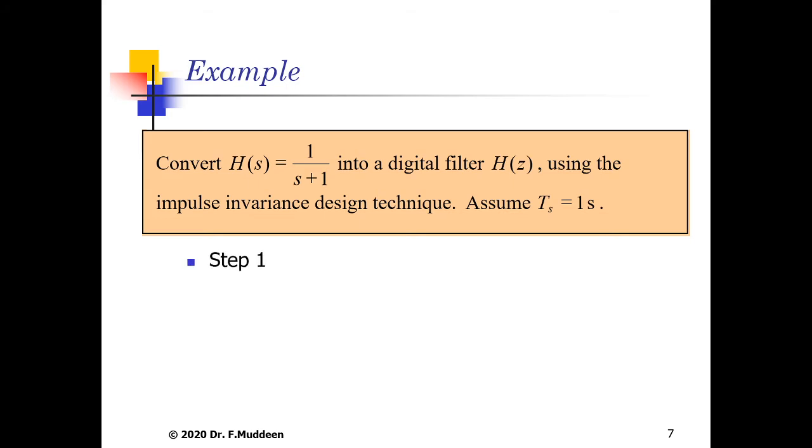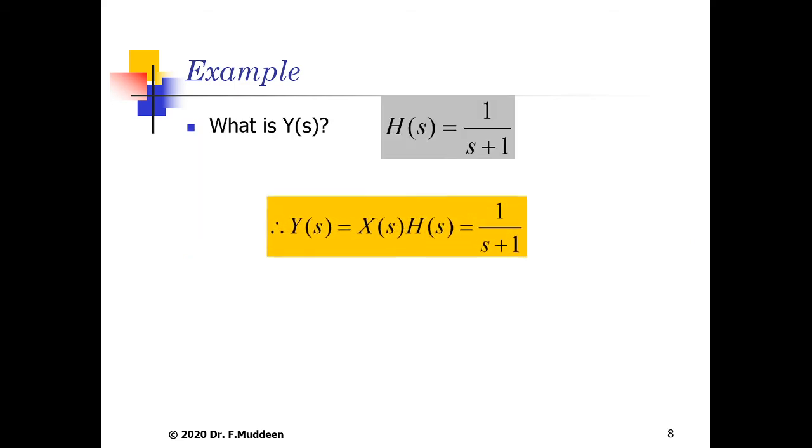So the first step is that we need to figure out what is X(s). Basically, since we're using x(t) as an impulse, we check the Laplace table. The Laplace table for impulse in time is just going to be 1 in the s domain. Because you also know that Y(s) is equal to H(s) times X(s), and X(s) here is going to be 1, that means Y(s) is basically just going to be H(s), as seen here.